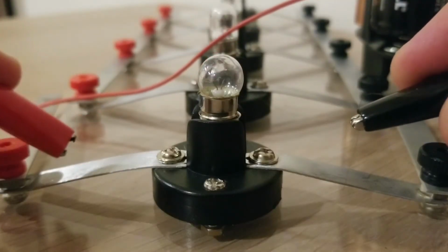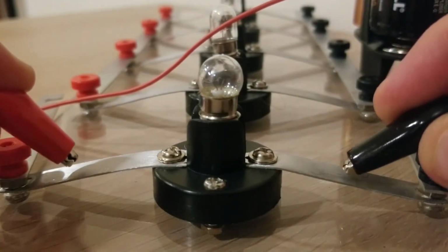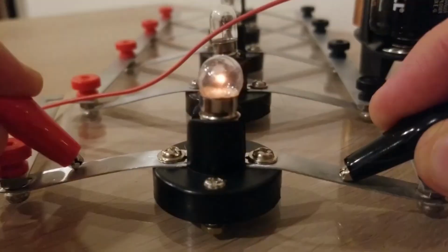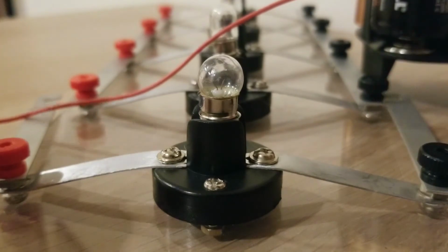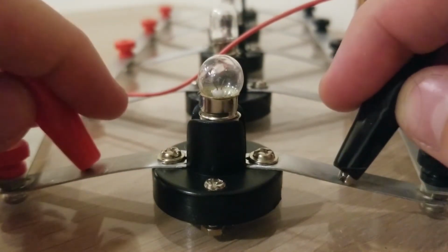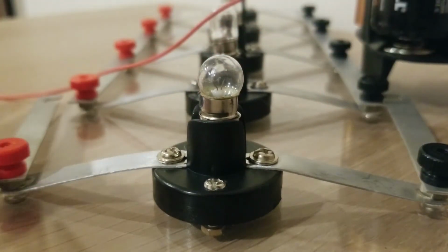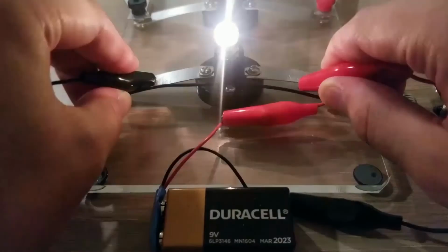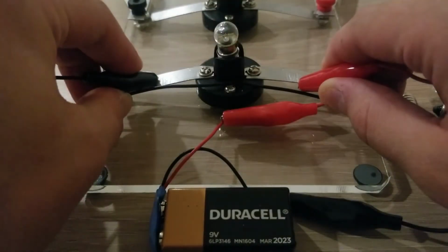In fact, 6 volts from 4 AAs is almost enough to burn out your bulb if it is alone in the circuit. Watch how the same 6 volts from 4 D cells behave instead. Because D cells are larger batteries, they have less internal resistance, allowing them to produce just enough extra current in your filament to break it. Likewise, watch how 9 volts also breaks your bulb.